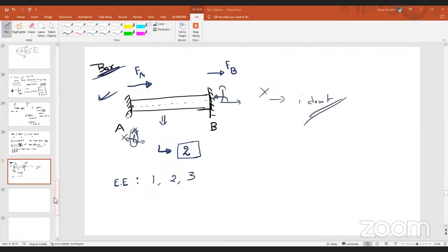Okay, why only 1? Only in the horizontal direction. The unknown forces or unknown displacements will be generated along the axial direction only. Even if I consider summation of forces in y equal to 0, or even if I don't consider it, this value will be equal to 0. Why? Because the forces are not existing along the y direction.